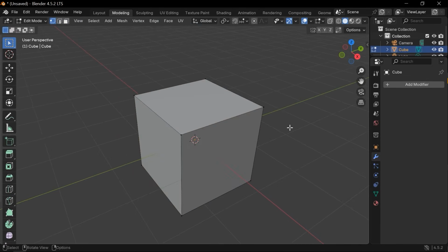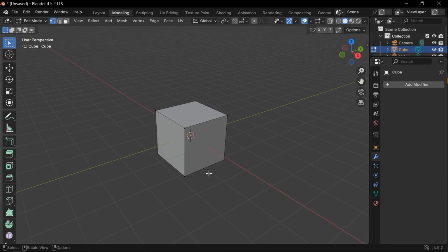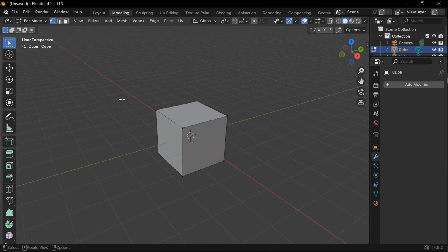Alright, these are the main components of each 3D model. For a complicated model, we have more vertices, more edges, and more faces. For example, if you want to create a pipe, you need a cylinder 3D model and you need to shape it and curve it, and curving it needs more edges. Make sure to keep your polygon and face count small, because a large number of polygons can be heavy to compute. Alright, now let's introduce the modeling tools.